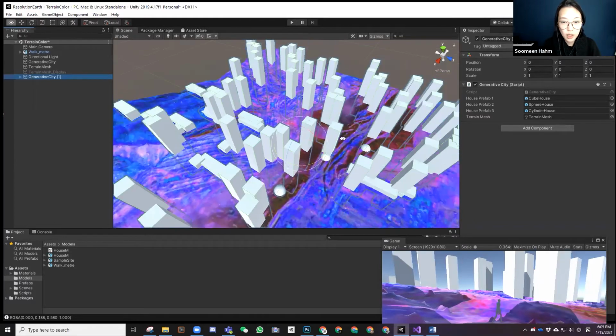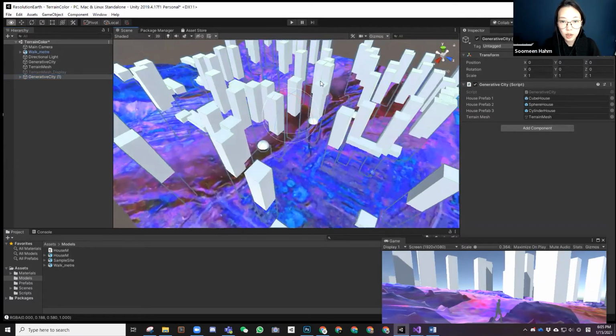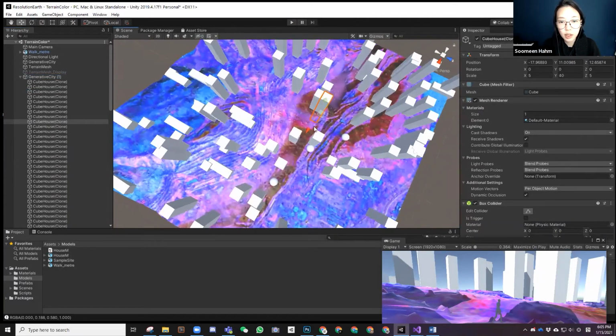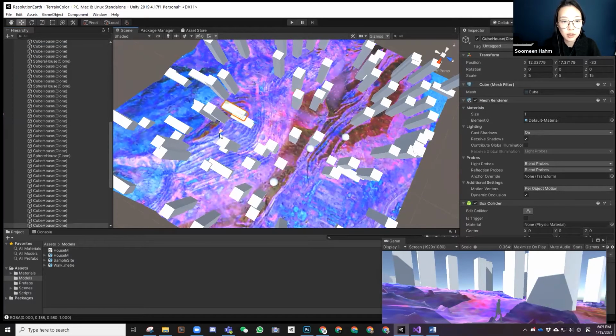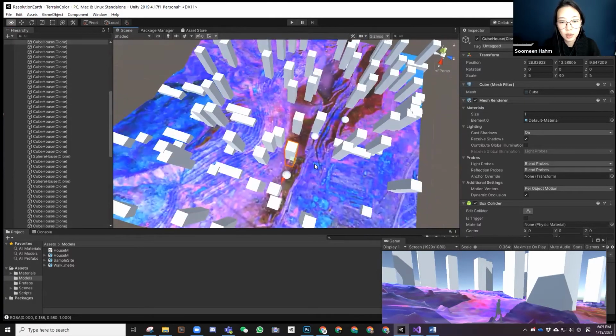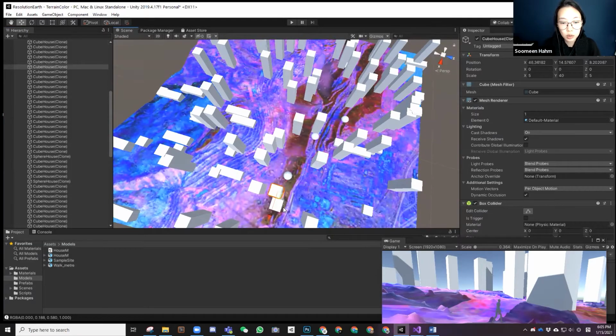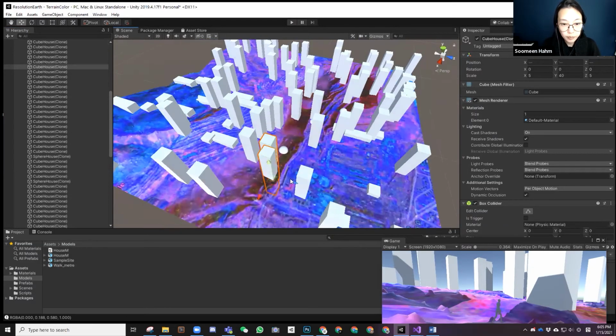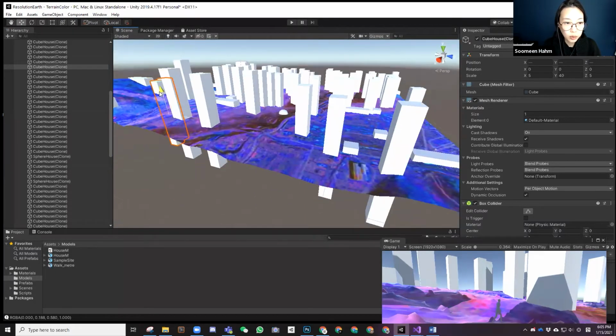That's how you can bake your geometries, and after that you can manually delete a few things and move things around. You can even export this as OBJ to Rhino by importing a plugin, which I will also show you in a bit.